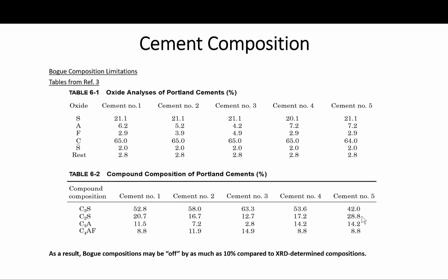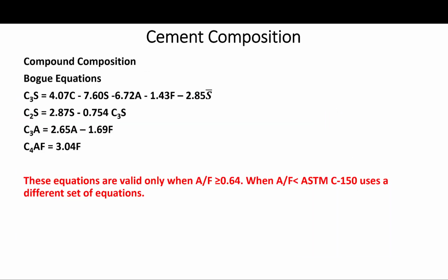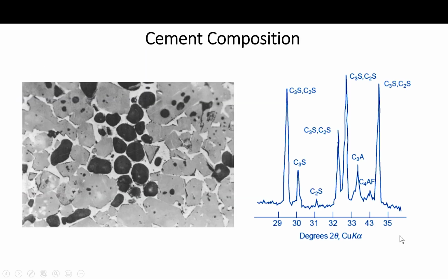However, as mentioned earlier, it requires special instruments and vast and thorough knowledge of the crystal structure and the chemistry of potential phases present in the clinker. So you have to know. Of course, you have to create a library of the potential crystal structures of the potential compounds that you believe are present in the clinker or the cement you are analyzing. So just let me elaborate a bit more. Let me go back here a bit. Just a few more words about the XRD method.